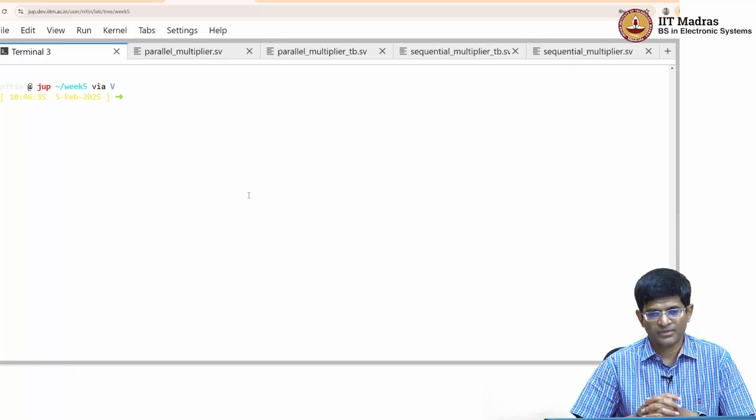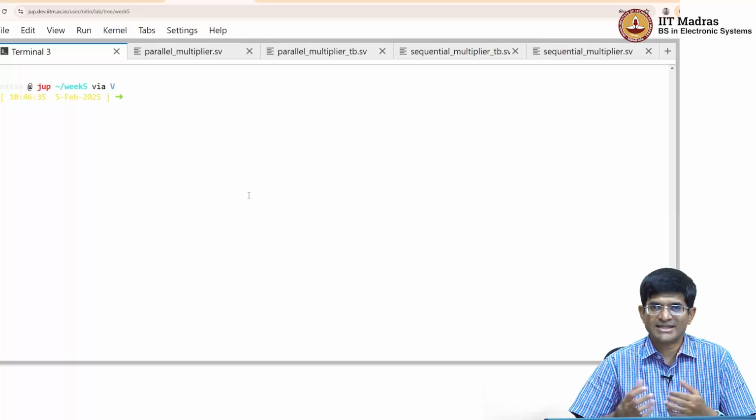Now, the way Yosys works is you need to read in your Verilog file, and then you need to give it a synthesis command, right. The synthesis command could be broken up into multiple stages. Either you can go through and give it the individual stages, like do the basic processing, extract the finite state machines, do optimizations, do certain other kinds of optimizations and so on, or you could just go ahead and give it one command saying something like synth_xilinx, which has a pre-built set of optimizations targeted towards Xilinx FPGAs, right.